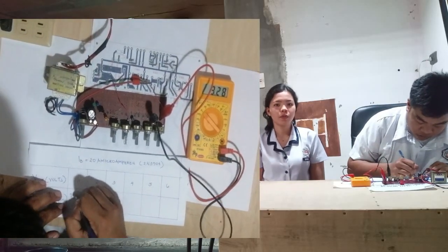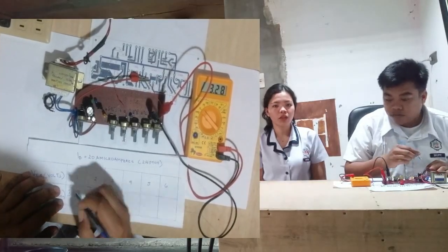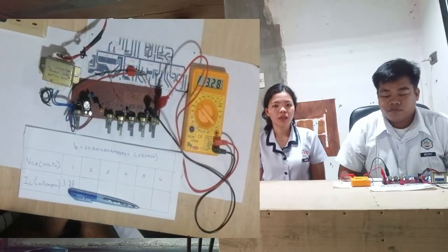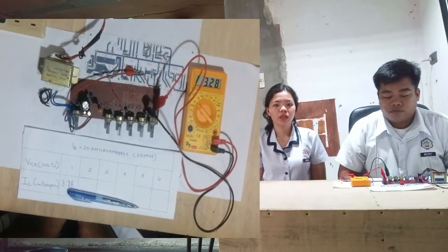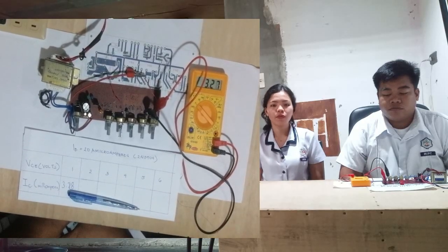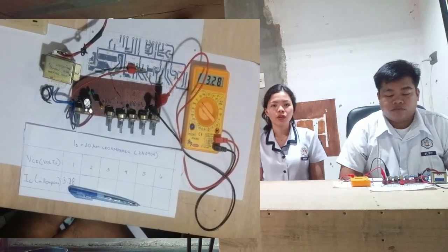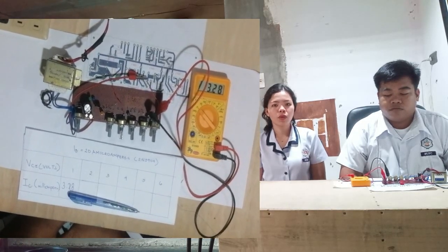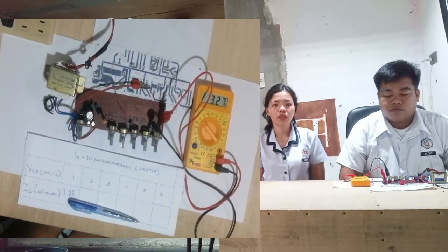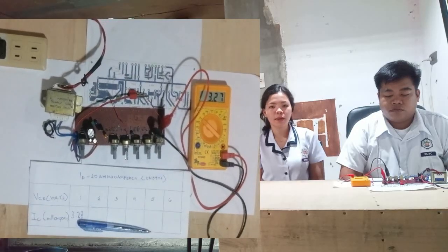Now, complete the table in figure 3-5 by adjusting collector emitter voltage to the remaining values indicated and recording the corresponding values of collector current. To do this, simply repeat steps 9 and 10 for each value of collector to emitter voltage indicated. Your completed table will show how collector current varies over a wide range of collector to emitter voltage values when base current is equal to 20 microamperes.